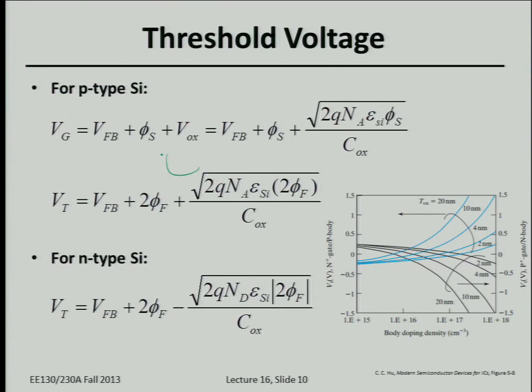That's an important voltage for us to keep in mind, because if we apply a gate voltage that large, the surface becomes n-type, and we can start to accumulate electrons at the surface rather than continuing to deplete the bulk of the silicon. As you increase the gate voltage to be more positive, you're adding more positive charge on the gate, so you have to add more negative charge in the silicon. Once you reach the threshold voltage, most of the negative charge you're adding is due to mobile electrons rather than further depleting the surface more deeply.